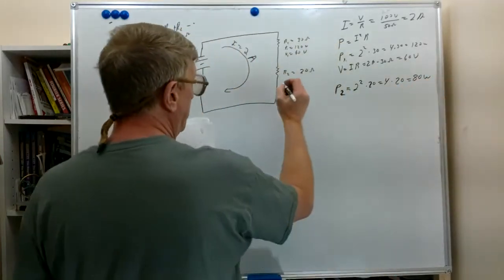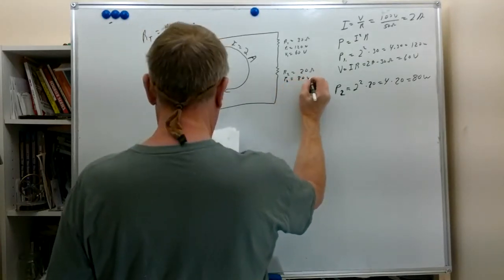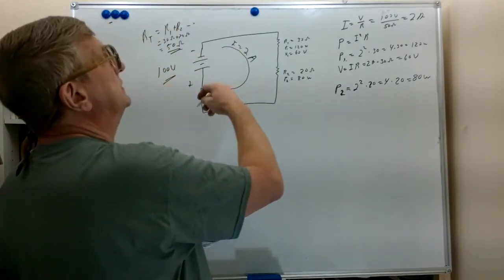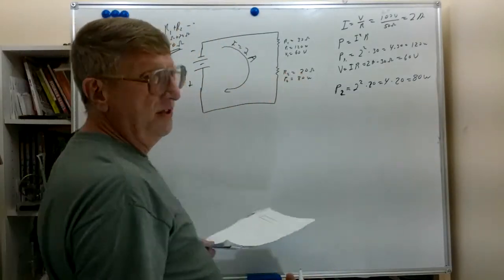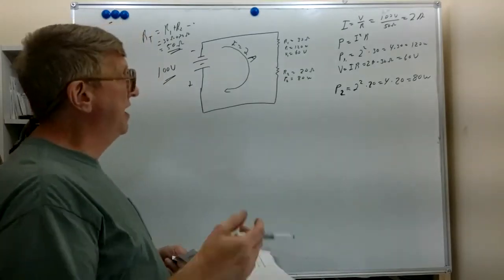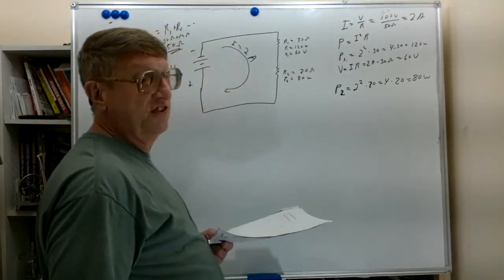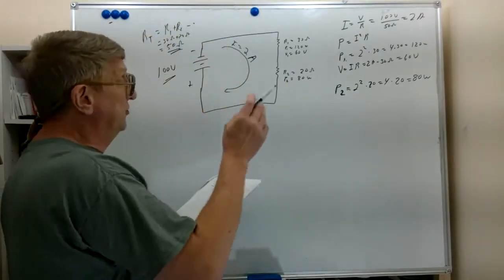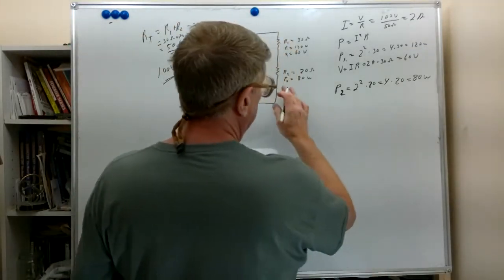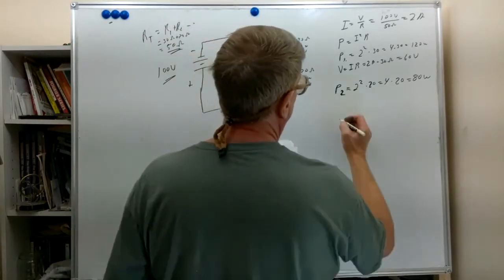So we have a power 2 of 80 watts, which is basically the amount of heat that R2 will be creating, and will require to dissipate into the air. And as you can see again, that's going to be a substantially physically large resistor to dissipate that much heat without burning up. We're going to calculate the voltage on that particular resistor.